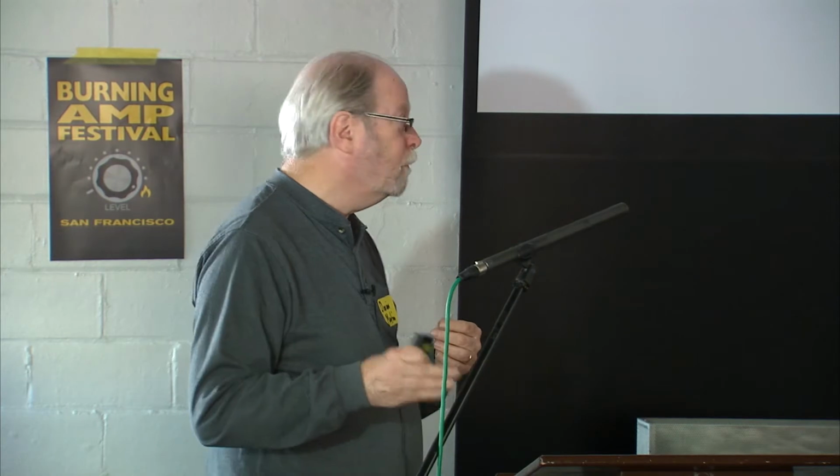The second type is a cancellation, where you take your input signal and the output signal of an amplifier. You adjust the output to match the level and the phase of the input so it cancels, and whatever's left, again, is the nonlinearity of the amplifier or noise or whatever it adds. This has also been used for a very long time.